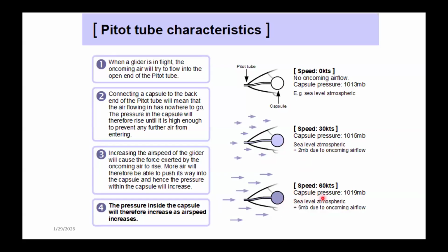But what I want to point out to you, remember how small 1 millibar was? From 13 millibar to 19 millibar, so 6 millibar of pressure, and remember that was 0.01, way down there on the PSI. So if you put your mouth on that pitot tube and blow, you put 5 PSI in there, you can damage something. Don't put pressurized air in on that line, or not that kind of pressurized air. Okay.